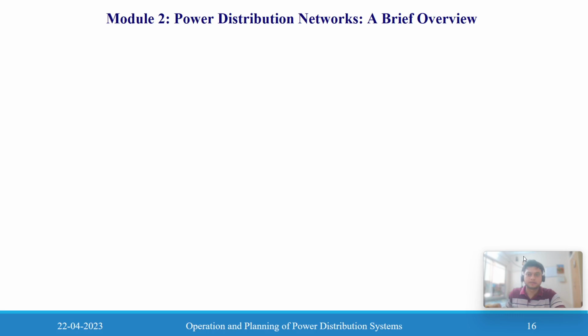Okay, so there is ambiguity like that. According to Ackermann, purpose and location define distributed generation, and the location should always be in the distribution system, not in the transmission system. For the distribution system, you can place it either at the primary distribution system or the secondary distribution system.